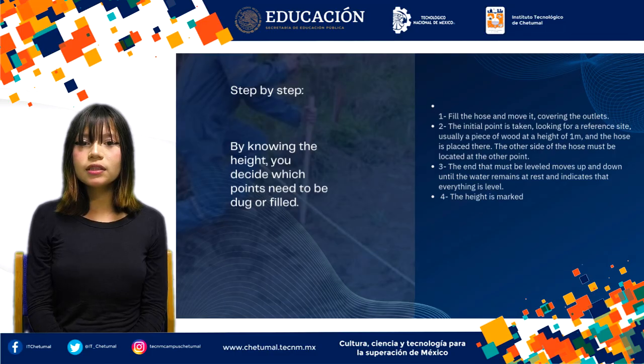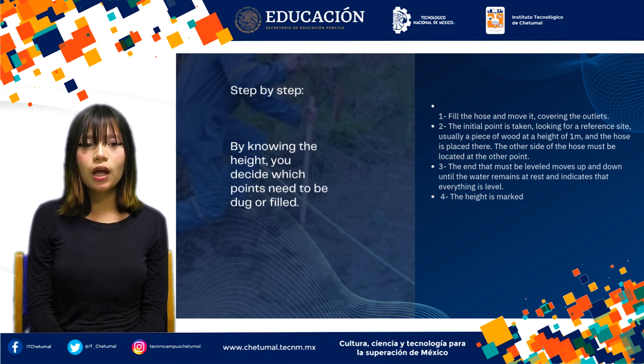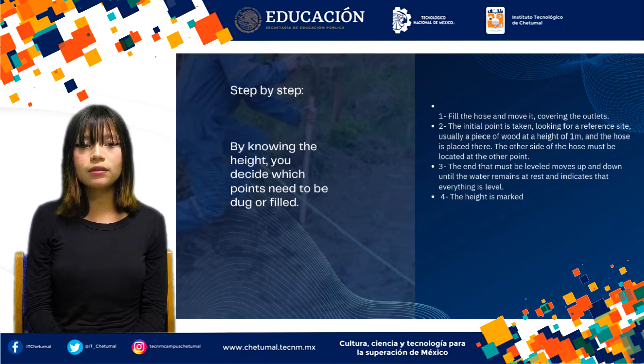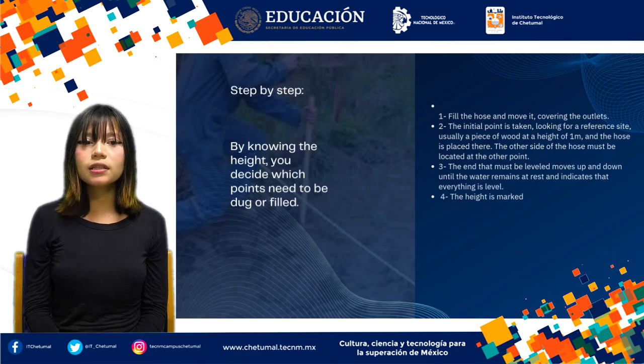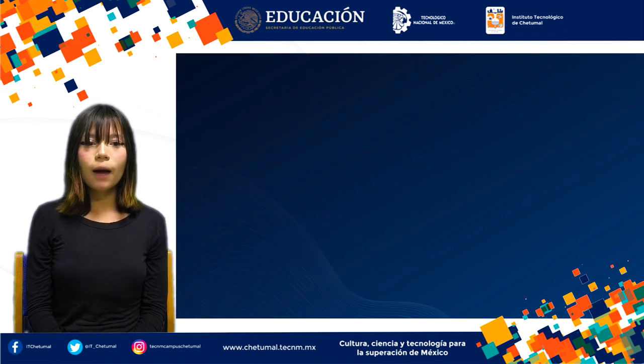Proper placement. It is essential that rebars are placed with their proper concrete cover to prevent corrosion and ensure their structural capacity. Armex is a prefabricated reinforcement material used to speed up the construction process and ensure proper steel distribution in structural elements. What is Armex? It is a set of pre-assembled rebar that forms frames or reinforcement structures for columns and beams. By being pre-assembled, it simplifies the construction process and reduces errors in the placement of reinforcements. Common uses.